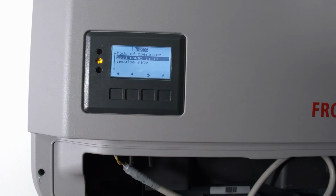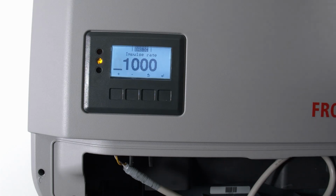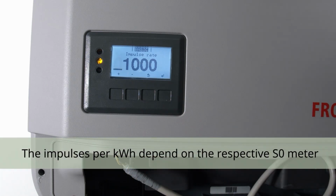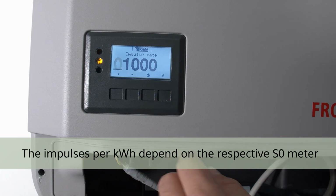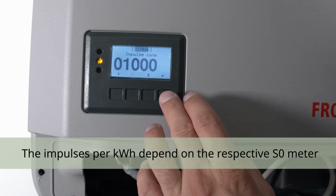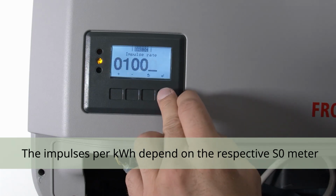Here it is the impulse rate. Under impulse rate, we can now set the impulse rate of the chosen S0 meter. In our case, it is written in the manual of the S0 meter: 1000 impulses per kilowatt hour, and therefore please choose the corresponding impulses that you have on your S0 device. Then we confirm these settings by clicking the enter button.